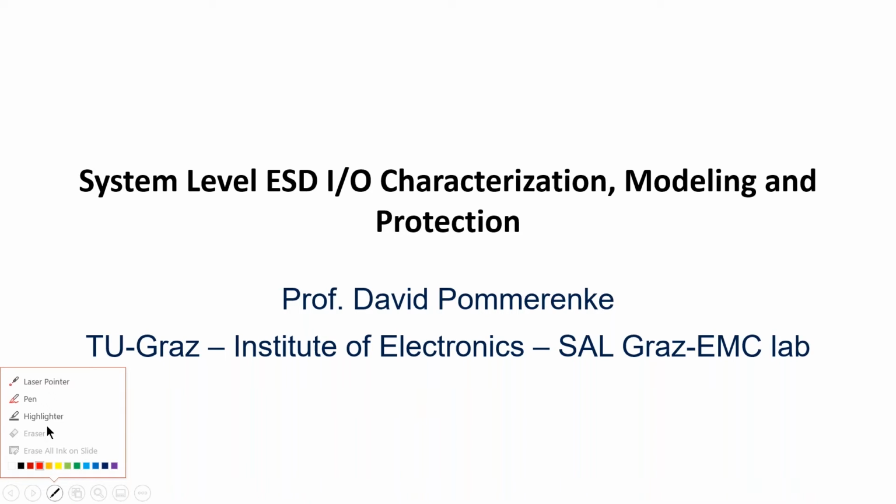As I tried to mention, the varistor really depends on what size the varistor has. There are quite big ones, and they can then provide a big capacitance, but there are also very small ones, and they have small capacitances. So in the end, it really depends on what kind of system you would like to protect and up to which level you would like to protect your system.